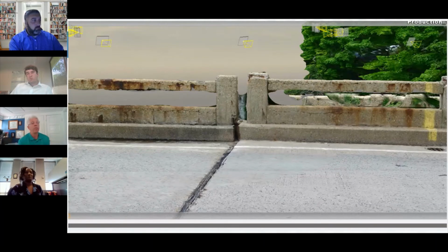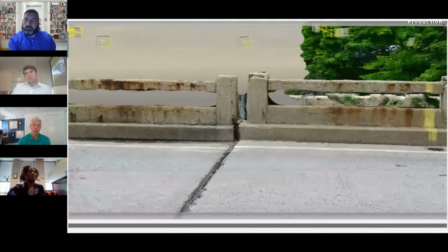Now you take a model, if I'm doing it for inspection purposes, the registration to exact state plane coordinates is probably not as important, because you're just really trying to show that item. But in the project we saw before, registering that into coordinates is really key. That's why the project in Houston County worked out so well: surveyors had already collected that data, and it basically had the ingredients to let that mostly automatically get done.